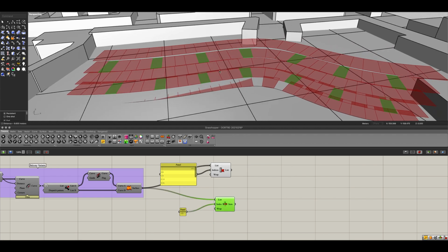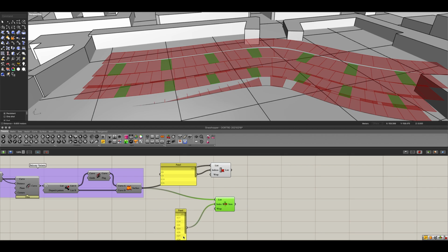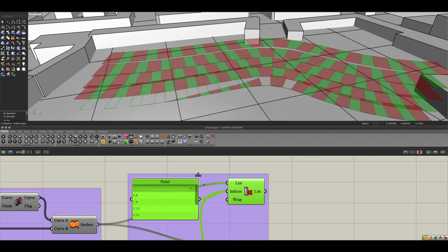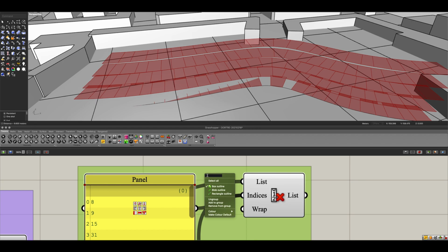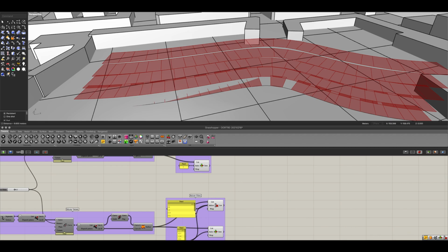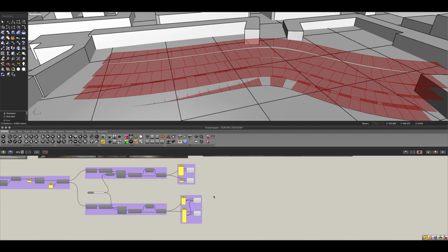And now you can see here we have the shapes we need to place in our stair variants. Of course, we also want to take these values off of this list, so we just need to connect it in there with our shift key. And now we have the proper isolated items, like so. Let's clean this up a little bit here. Make this one also into a group. I'm going to call this one balcony filters. Like that. You can also clean this up a little bit. It's a bit badly positioned. Yeah, like that.